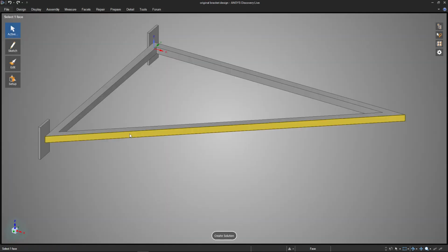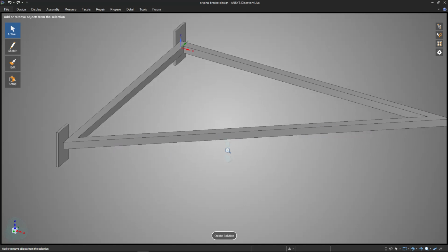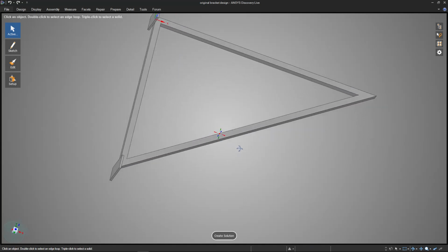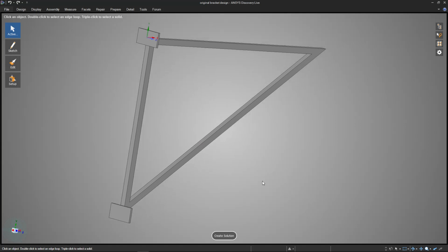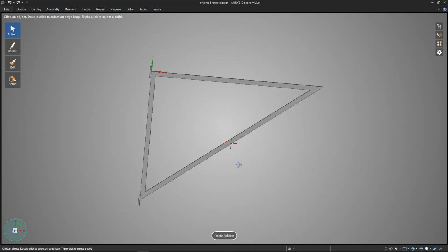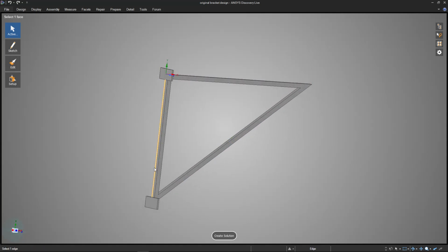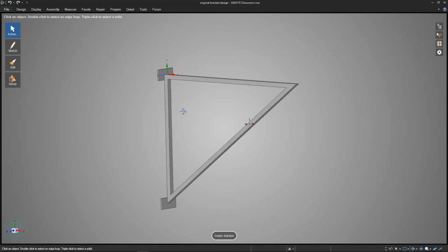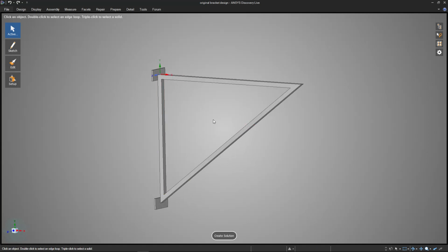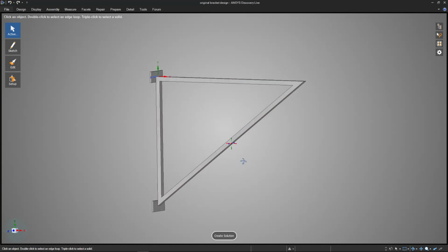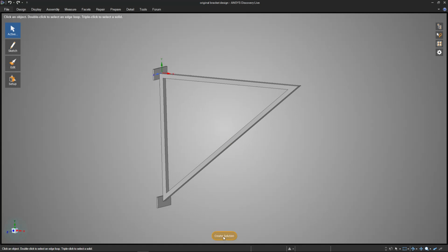Double clicking that and opening it, it is, yes, the exact same one that I had created in Fusion. What we're going to do is see, when I put a force on the end of this design and hold these two mounting brackets fixed in space because they're drilled into the wall, where this thing is going to have the greatest and least force or stress inside of the object. In order to do that, I'm just going to click Create Solution.